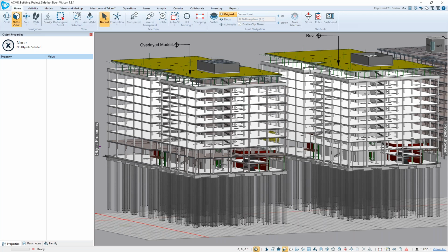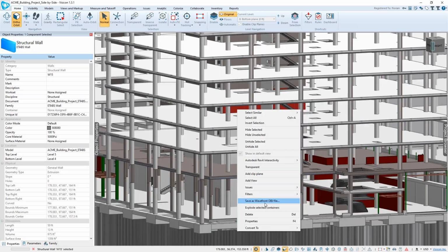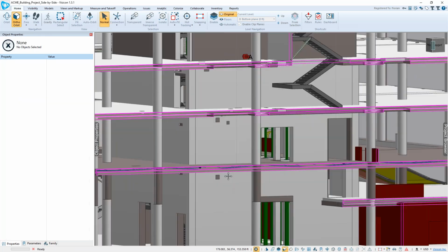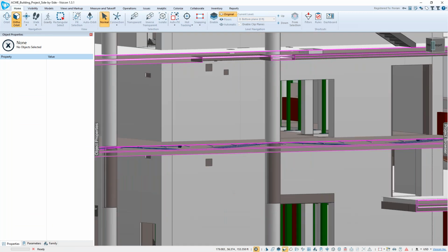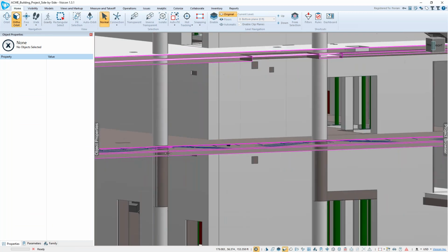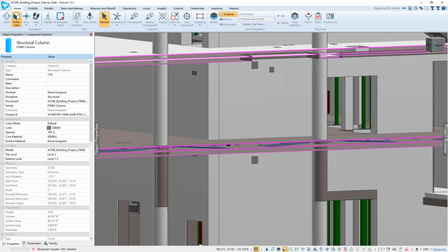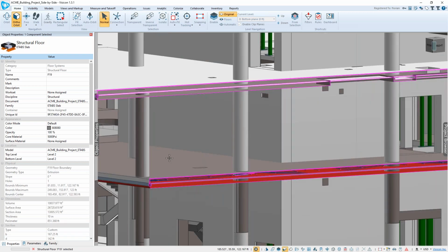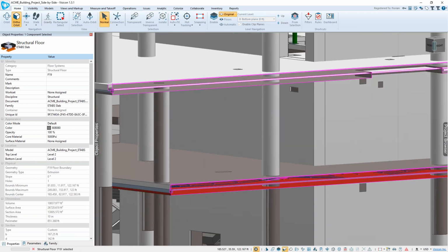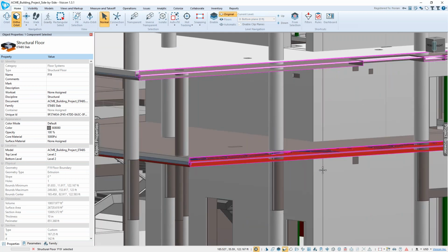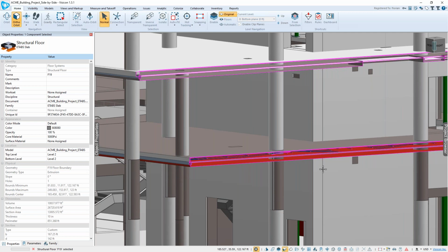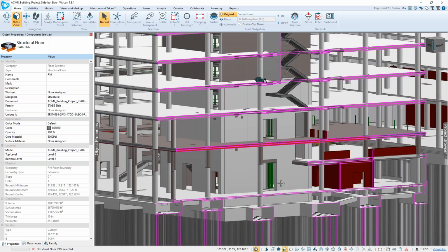If I zoom out, and I know I've done level 2, I want you to observe that they're actually post-tensioning tendons. So here at that level 2, we're actually looking at the ETABS model, the ETABS columns, ADAPT columns, REVIT columns, all superimposed. That gives me great ability to check the consistency between models. That's all I wanted to highlight on the left side.